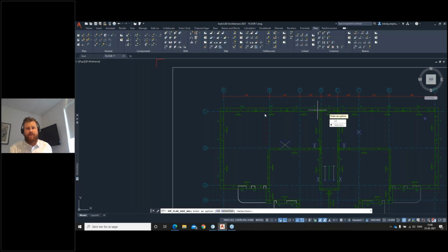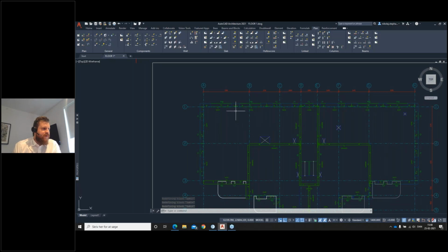And now I can select which order I want to save them in to completely control the numbering of the elements. In my case here, I want the computer to work for me again. So I'll just click all sandwich walls. Where should we start? Well, let's start at 001. And it'll then work its way through, scanning if any elements are the exact same and so on. So it'll really optimize the way that the numbering gets done. But otherwise, number 1, it'll start from what it sees first because it's a computer, of course. If we want to control it, again, we just pick the order we want to save them in. So here now, we got some element numbers as well on our elements.